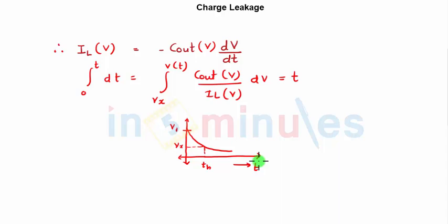how, if we assume the initial voltage to be V1, we started deteriorating, or losing out on that value, with some equations. And then we further went ahead and saw some other leakage currents which reduced the hold time further, and we understood that we have to have a minimum frequency of operation for our circuit, and in order to not lose the value, we should also have refresh mechanisms in case of dynamic circuits. So minimum frequency and refresh mechanism we'll be seeing in the further clips.